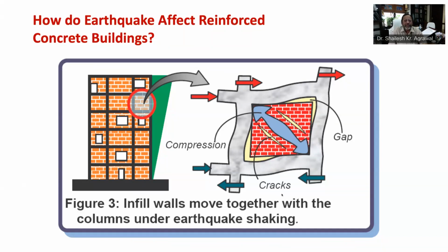As we already know, masonry is a brittle material and therefore these walls develop cracks once their ability to carry horizontal load is exceeded. Let's consider these infill walls as sacrificial fuses in buildings. That means they develop cracks under severe ground shaking but help share the load of beams and columns until cracking. The earthquake performance of infill walls is enhanced by mortars of good strength, making proper masonry courses and proper packing of gaps between RCC frames and masonry infill walls.